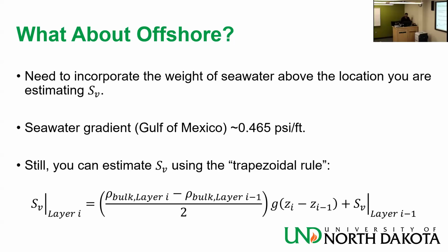And I'm expecting to hear something near 1 psi per foot. Okay, so any questions about how we estimate SV in the real world?